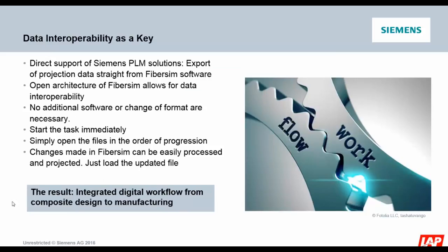As I have demonstrated, the projection file generated by the FiberSim laser projection module can be easily handled by the LAP software. Thanks to the open architecture and data interoperability with FiberSim, you may immediately start the task in the LAP software. No additional software for importing CAD data is needed. Files can be opened in the order of position. If changes are made in FiberSim, they can easily be projected by uploading the updated file. The result is an integrated digital workflow from composite design to manufacturing.